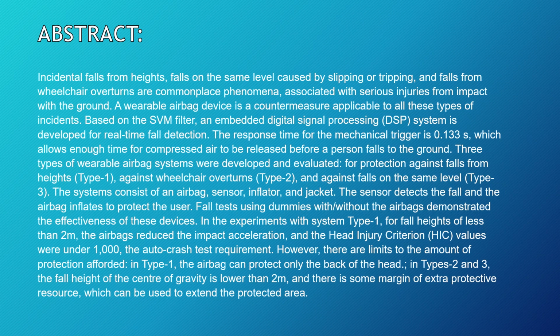Based on an SVM filter, an embedded digital signal processing system is developed for real-time fall detection. We can also use a DMP, digital motion processor, for filtering the motions. The response time for the mechanical trigger is 0.133 seconds, which allows enough time for compressed air to be released before a person falls to the ground. Once a fall event is detected, the system can trigger a response.